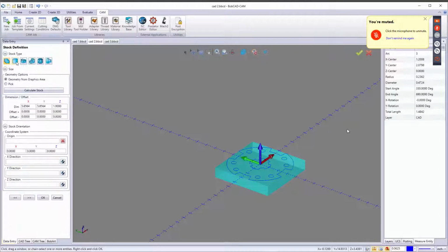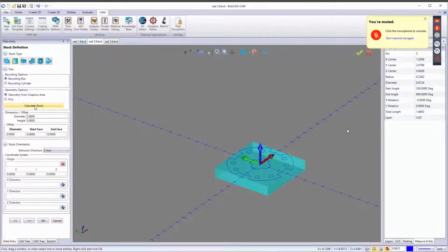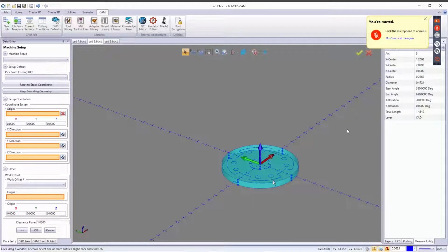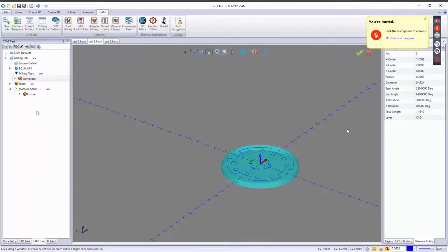And then here, let's go ahead and use cylinder, and actually let's do bounding cylinder. Look at our overall size here, and then on this one let's go 7 as a diameter, and total depth let's go 0.55. Just kind of throw you guys off there. All right, so we'll hit next. We'll keep it in the center there. It should be fine, and we'll okay that.